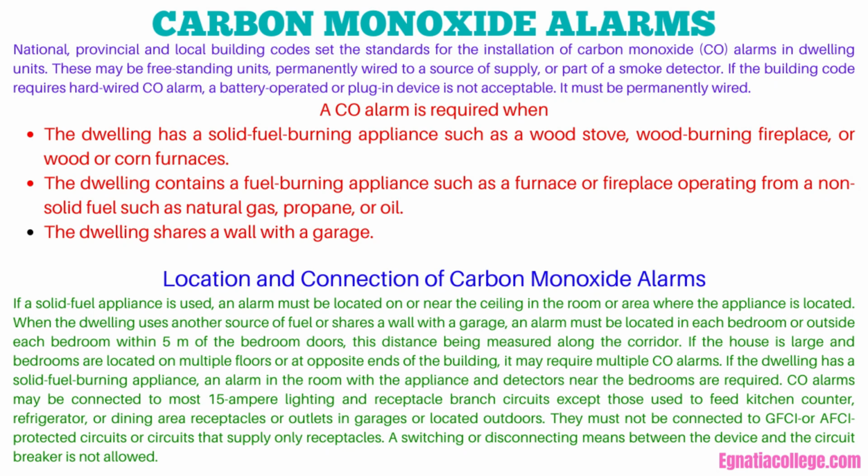A CO alarm is required when the dwelling has a solid fuel burning appliance such as a wood stove, wood-burning fireplace, or wood or corn furnaces. The dwelling contains a fuel-burning appliance such as a furnace or fireplace operating from a non-solid fuel such as natural gas, propane, or oil. The dwelling shares a wall with a garage.